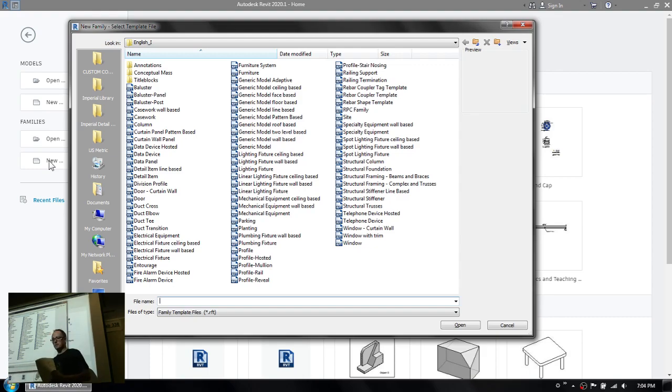If you make use of Revit's out-of-the-box cabinets for upper cabinets in the kitchen, those cabinets require a wall to be placed in before the cabinets will go. The upper cabinets require a wall to place those upper cabinets.